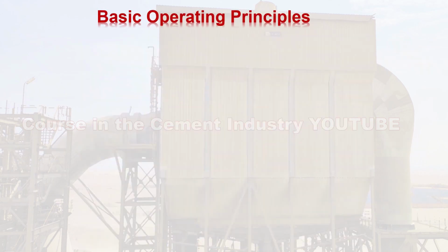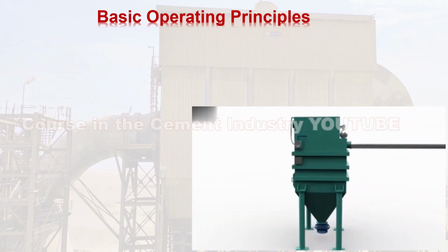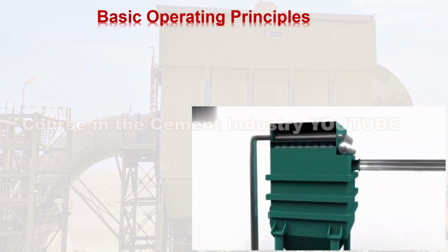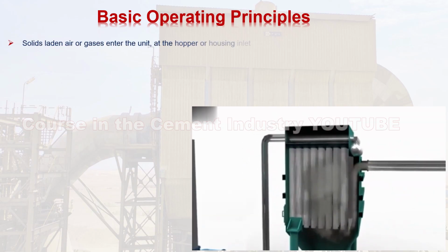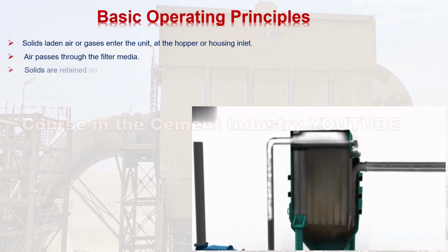Basic operating principles. Watch this video explaining operating principles for pulse bag filter, as it is one of the most important operating principles. Solids-laden air or gases enter the unit at the hopper or housing inlet. Air passes through the filter media. Solids are retained on the filter media surface.